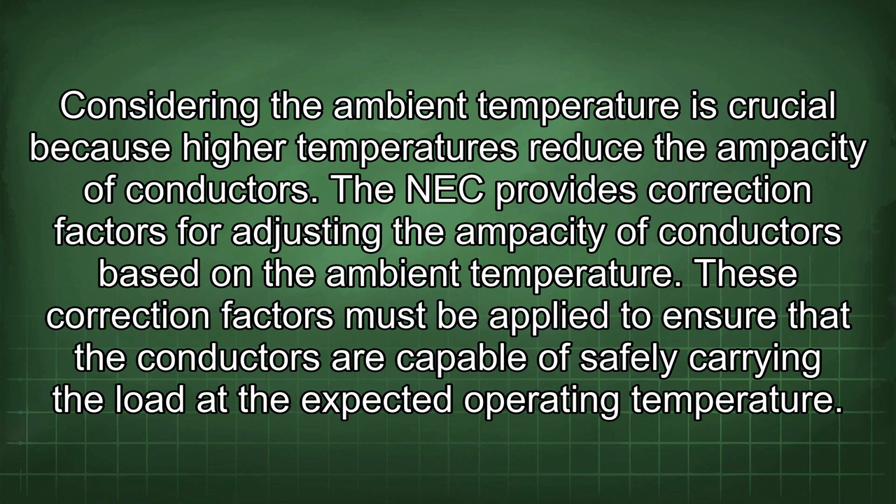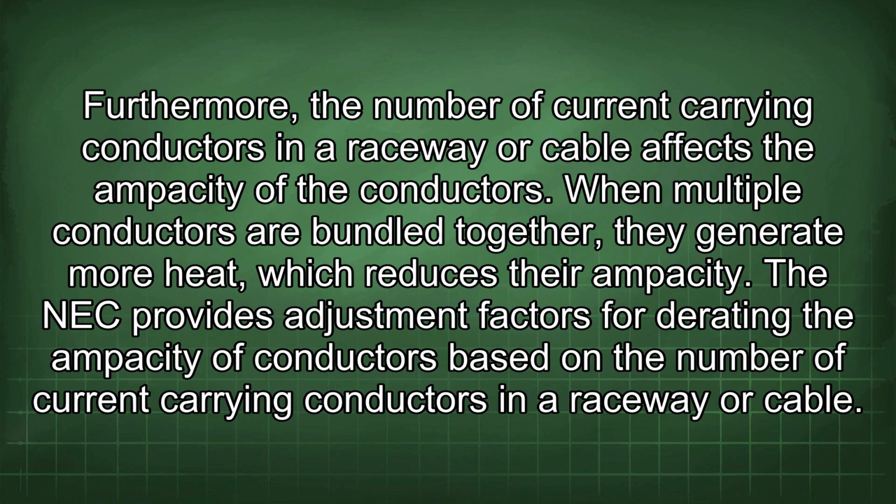The NEC provides correction factors for adjusting the ampacity of conductors based on the ambient temperature. These correction factors must be applied to ensure that the conductors are capable of safely carrying the load at the expected operating temperature. Furthermore, the number of current carrying conductors in a raceway or cable affects the ampacity of the conductors. When multiple conductors are bundled together, they generate more heat, which reduces their ampacity.